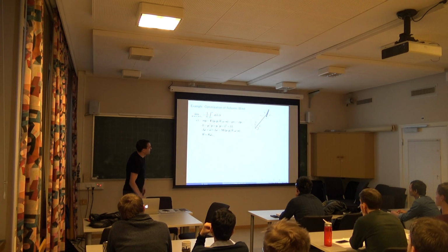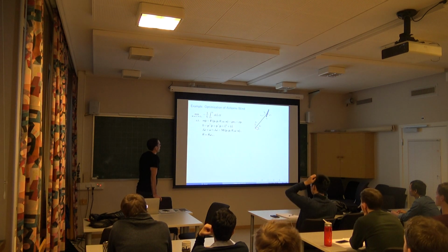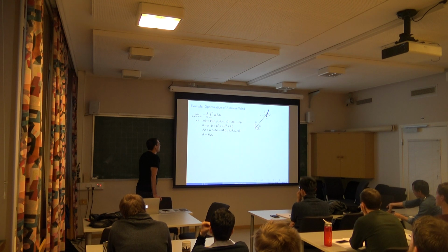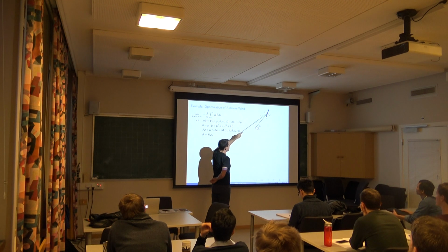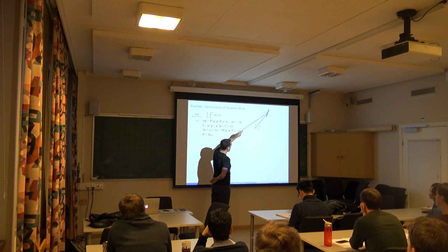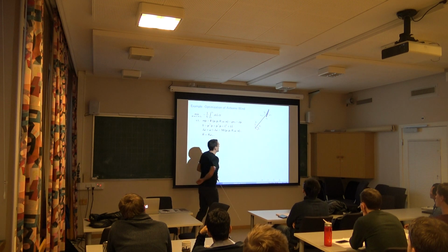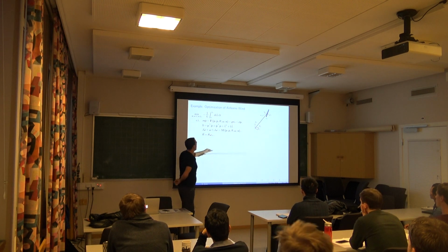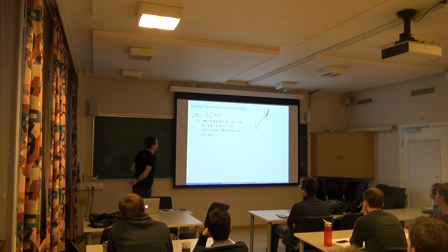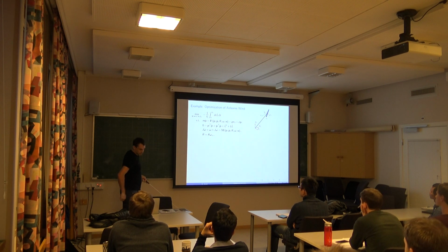So you can formulate that as an optimal control problem. We use this kind of approach I described with the pendulum. So we describe this as a completely free-flying thing with position and velocity, and you have the rotation matrix, and then we add the cable that forces this thing to be at a specific distance from the attachment point on the ground. So long story short, the model equations look like this using a DAE technique.